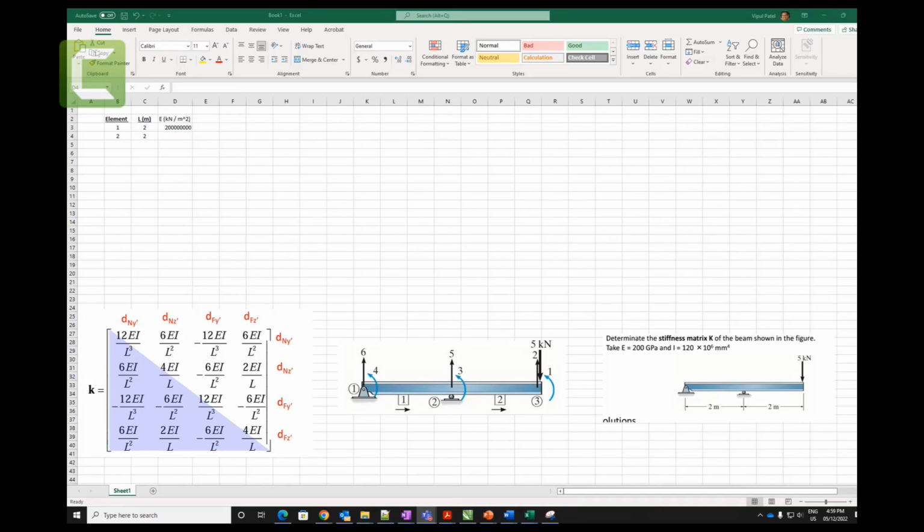Okay. All right. So just type these ones, E and both. Similarly, we have the same Young modulus for the second one. So you can click on that one, copy, click on these ones and just Control V. Just put it in the middle. That Young modulus is done.